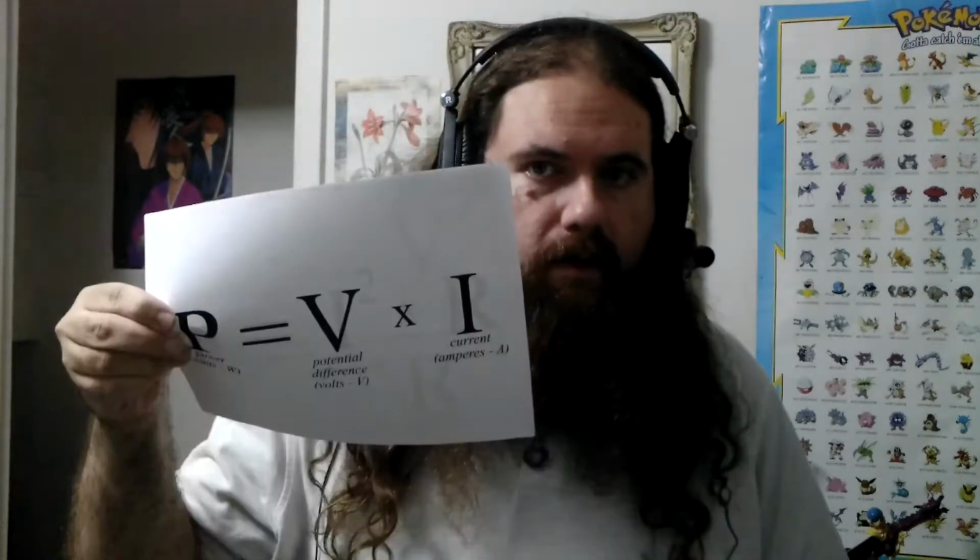Ohm's law and Joule's law. These are the two fundamental equations that circuit builders will be using all day, every day practically, to figure out what resistors they need, to figure out what currents will be flowing through devices, to figure out how much power devices will be using to make sure they're keeping under power limits, and to see what size heat sinks they have to put on heavier components.